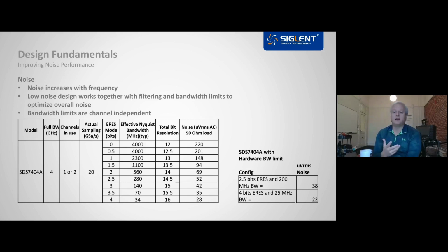Without the detail here to reference, analysis features as well as modes like filtering can quickly become impractical or useless. One important note here is that high frequency noise is a significant contributor to overall noise. So less expensive scopes with naturally lower bandwidth will typically show less noise. It's another reason why filtering capabilities can be useful and important. They can extend an oscilloscope's value to a wider set of lower bandwidth applications.